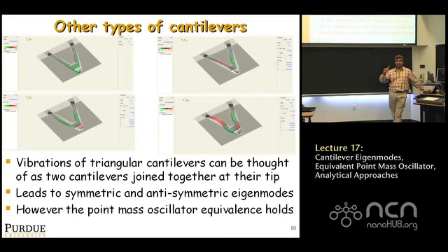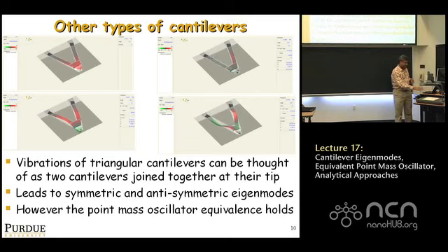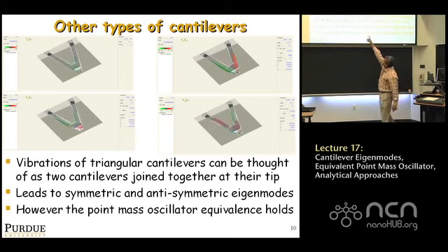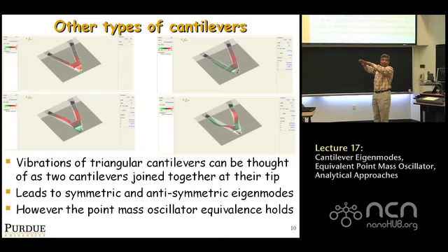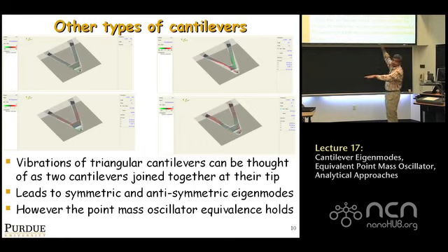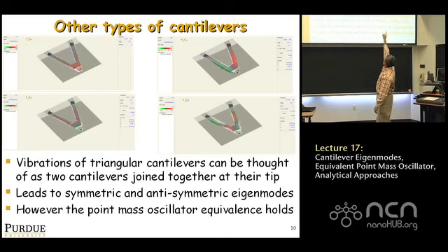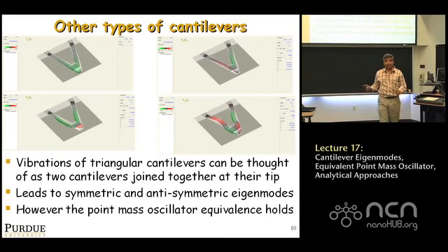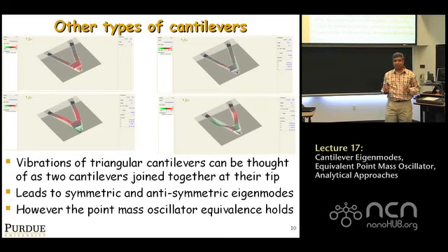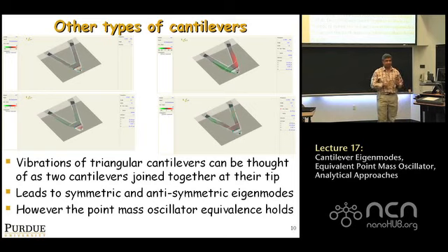It turns out you have this, the first bending mode, both go up and down. Slightly above that frequency, you have another resonance where they're going out of phase and they're twisting it. So the eigenmode frequency in the top left and the eigenmode frequency in the top right are actually not far from each other. They're pretty close. It's interesting. I mean, it's not very far apart.